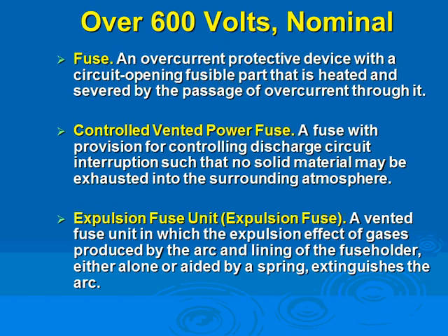If that fuse is inside a building, do you want this energy to blow up in the building and burn something? No. So they'll be non-vented. If this fuse is at the top of a 40-foot tower, a 40-foot pole, do you care what's going on right at the top? So you see the bam and big explosion come out and interrupt the circuit. So these are the controlled vented versus explosion fuses, sir.